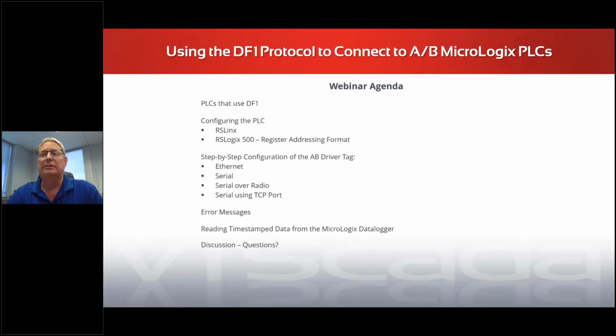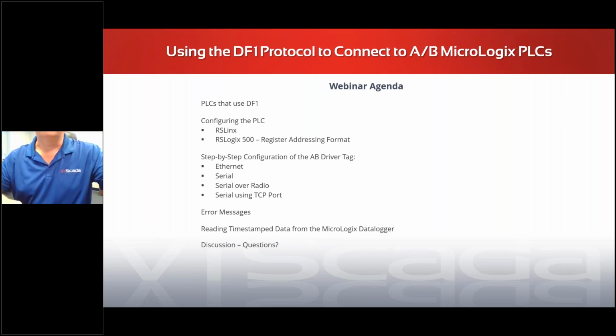Then we'll go through step-by-step configuration of the Allen-Bradley driver tag within VTScada, different scenarios for connecting, and then we'll quickly look at error messages and how you can troubleshoot a connection. And hopefully at the end, we'll still have some time to demonstrate the MicroLogix data logger. So we'll talk about that later on.